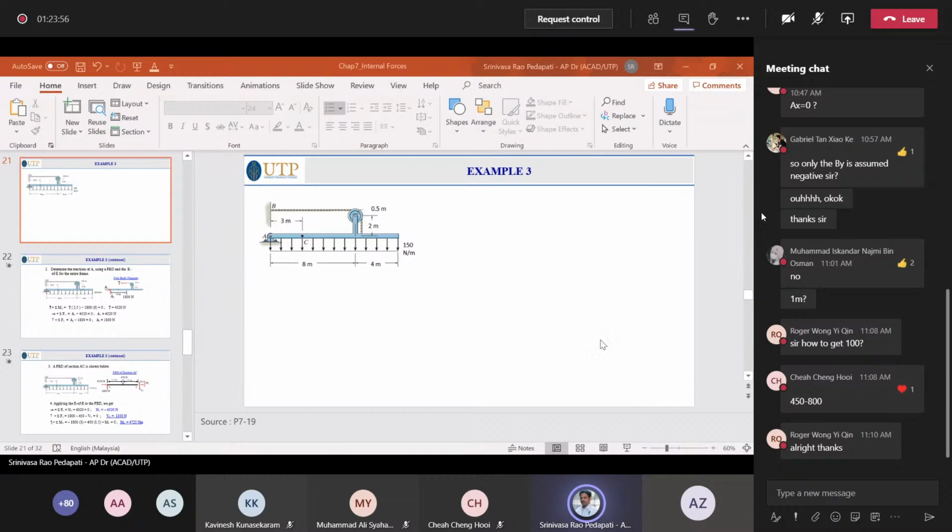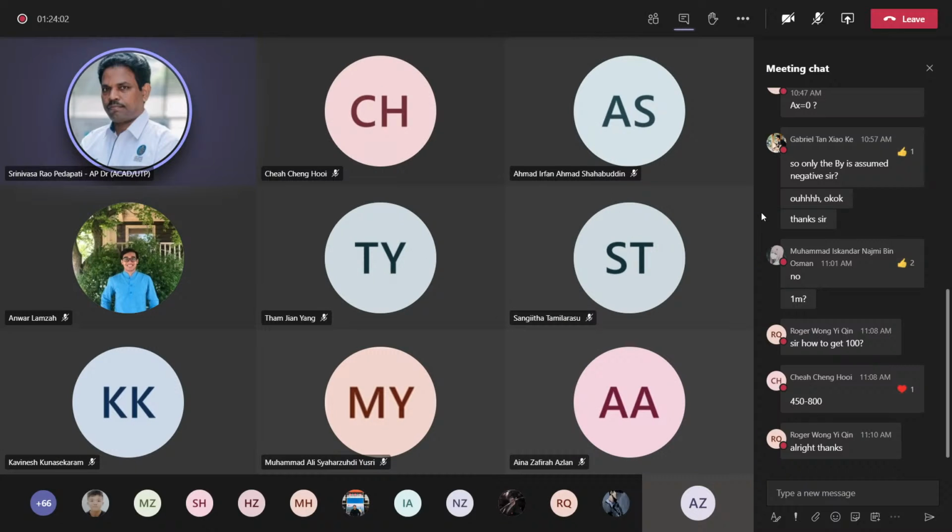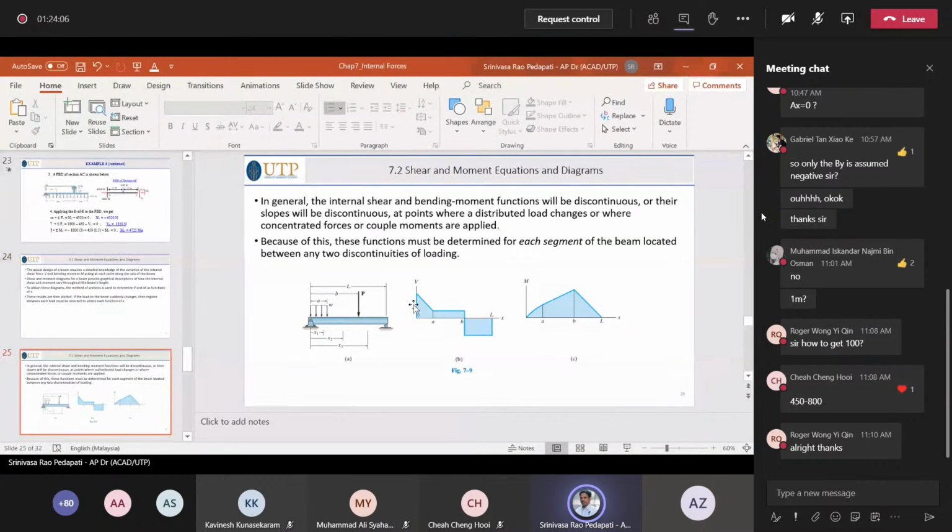If you apply your knowledge of the bending moment diagram to that beam, then you can answer why. In this case, if you see the slide that I showed, the middle part is subjected to more stress or more bending moment. Therefore we should provide more material or more area there.